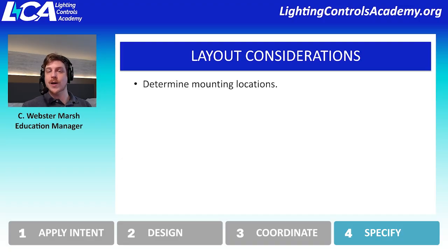It's also a good way to coordinate whether or not that keypad might get hidden behind a door, because if the keypad's on the door swing side of the door, the door when it's opened might completely block visibility to that keypad, which is oftentimes a bad choice. And so it's always good to have your keypad constantly visible when the door is open or closed. That way you really do get a chance to coordinate with the architecture of the project.